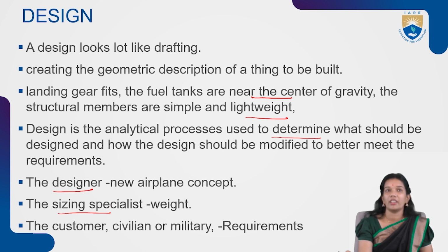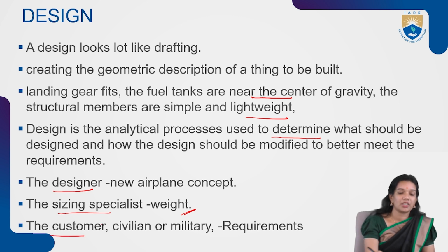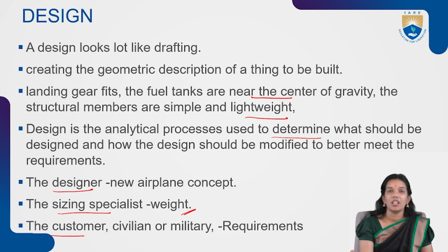I cannot design an aircraft without knowing my first estimates of the aircraft gross weight or the fuel weight. So to a sizing specialist, the initial estimates of what the aircraft is going to be is his definition. To a customer, civil or military, the requirements given by the customer are the definition of a design, or where the design starts from. And all the definitions are right.